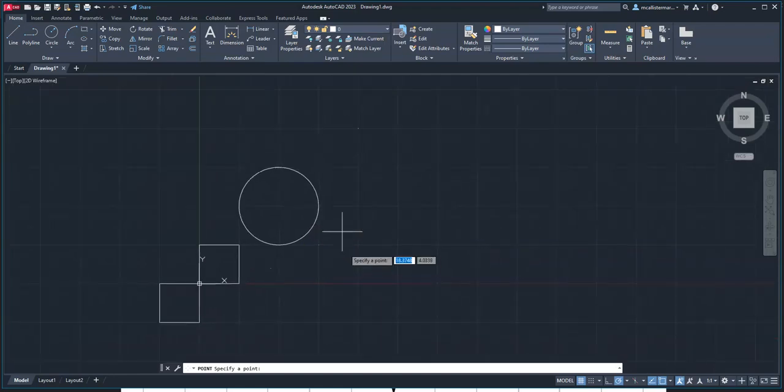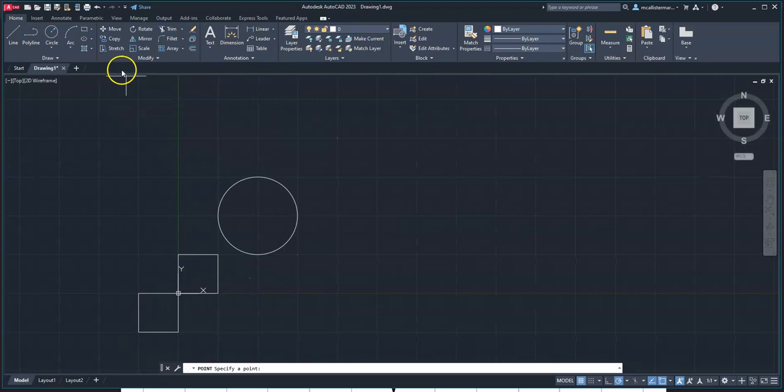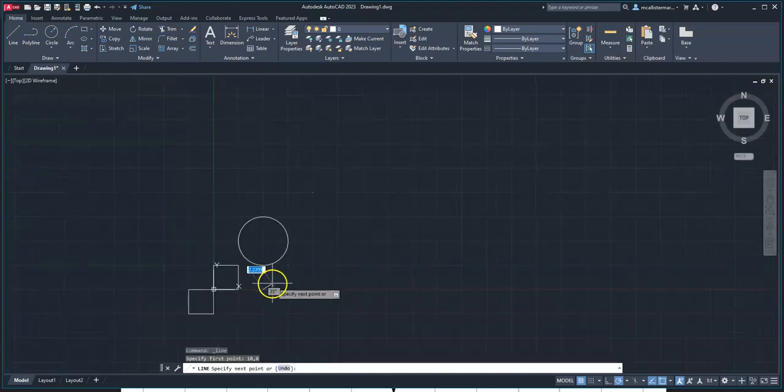This is how we go about utilizing the coordinate system in AutoCAD in order to place items that we are sketching or drawing. This will go right into the line command as well, but the line command is a little bit different in the sense that we can snap to a specific point. So I can say, let's go 10, tab 0, and hit enter, and it's going to start a snap right here.